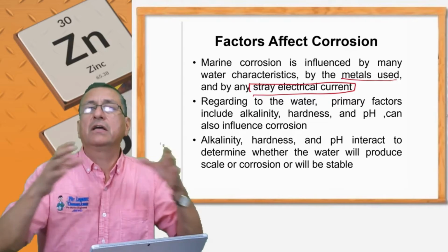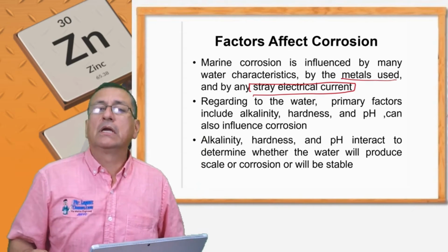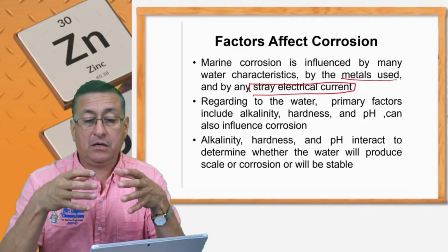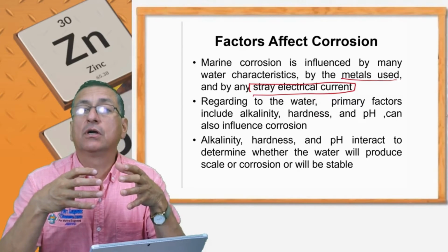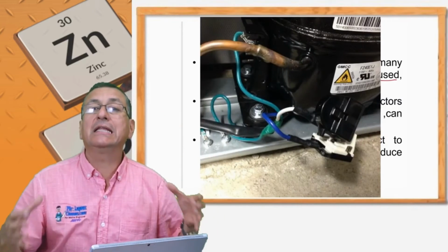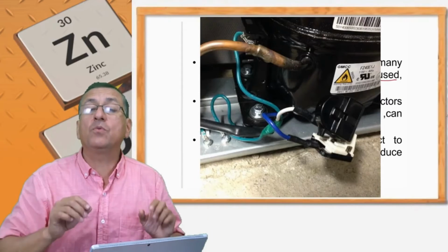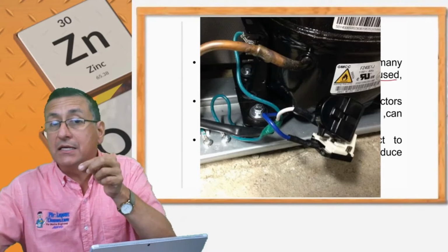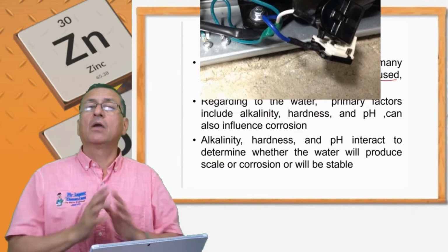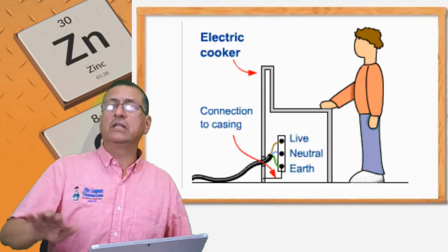The dishwasher has internally a motor, and the motor is spinning, no, at high speed. All right. When the motor is spinning, the coil of the stator and the rotor jump some electrons, and those electrons are stored in the case of the dishwasher. No? If the case of the dishwasher is not properly bonded, is not properly connected to the ground, to the bonding system, what happens if you suddenly touch the case of this appliance?